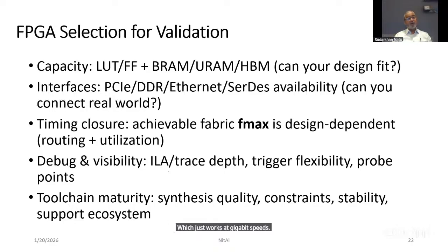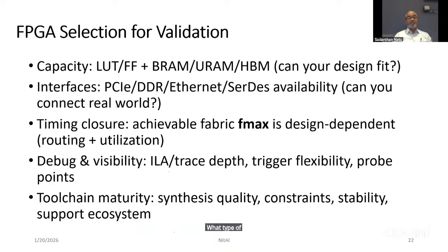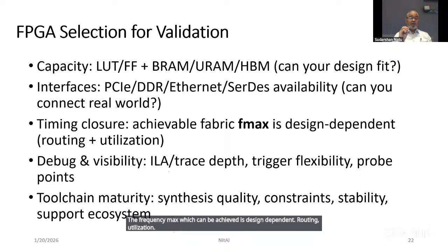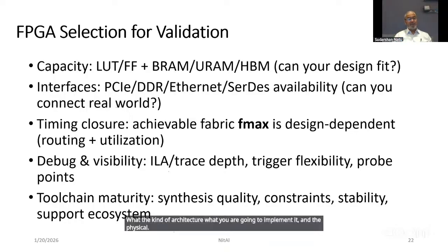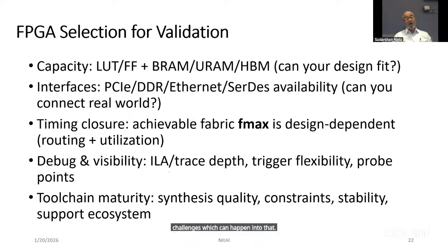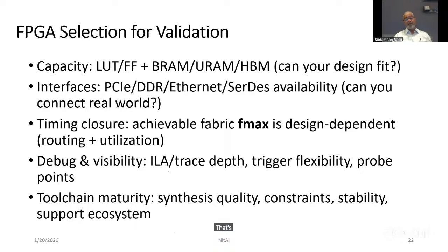Do you need that? Do you need to connect it to the real world? What type of frequency do you want to achieve? Because the maximum frequency which can be achieved is design dependent: routing, utilization, what kind of architecture you are going to implement, and the physical challenges which can happen in that. Then how you are going to debug and get visibility inside a chip. That's another big problem when you are designing a semiconductor.